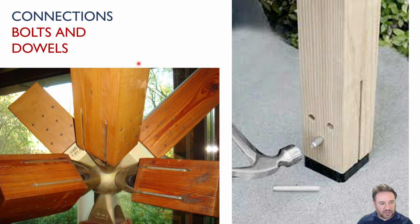In the case of dowels, I basically cut my hole the same size as the dowel. The dowel does not have a head. It does not have a nut. The hole is cut just a little bit smaller so that it fits in with friction. So in order to install a dowel, I'm going to have to use a hammer or something to force the dowel into the hole. Since the hole is just a little bit smaller than the dowel, they're about the same size, the friction fit between the two is going to keep that dowel in place. But from the point of view of design, it's basically the same. So we design dowels the same way that we design bolts. A dowel is just basically a steel rod.